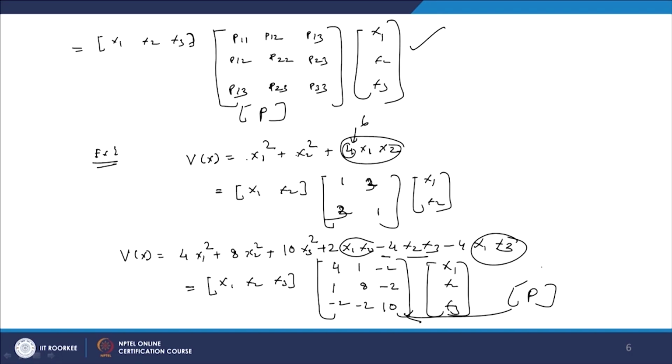Now, from this P can we get some idea about the eigenvalues of this P matrix, on which side they are lying, whether the left side or right side? And here I am not talking about the imaginary axis, because a real symmetric matrix involves elements on the real axis, that is, we will get the eigenvalues on this real axis, no complex conjugate elements. Then can this quadratic function be used for stability of the system? Now, first of all we will see how to handle this, that is, how to get the information about the eigenvalues of this matrix P.